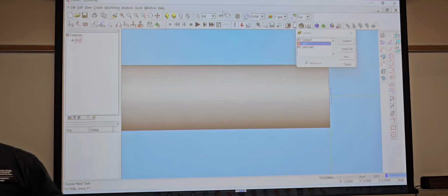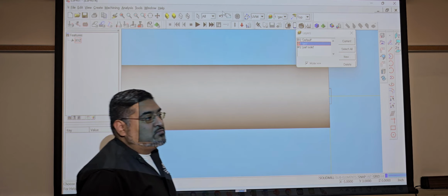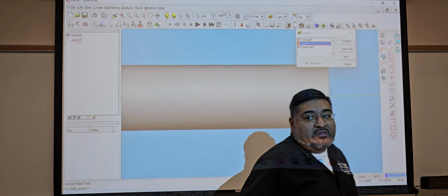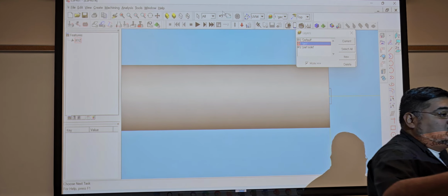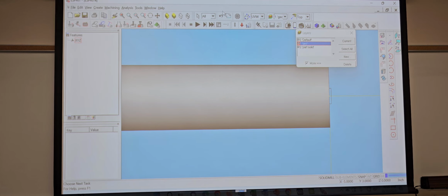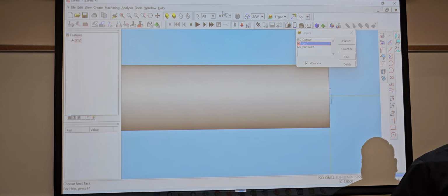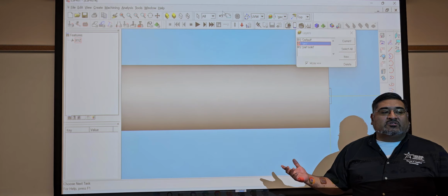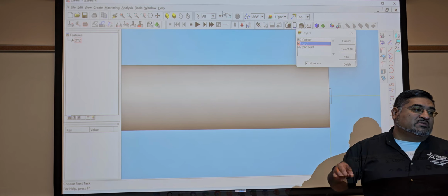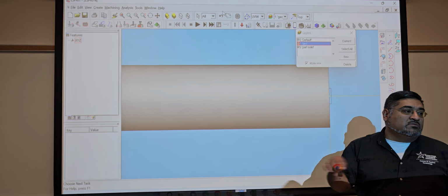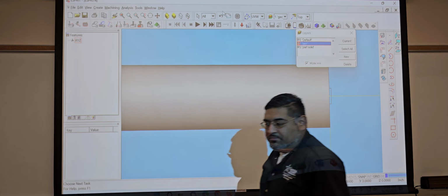Now, you could 3D print something like that, right? Yeah, but it's better to 3D print it with one that has a second filament, because you're gonna have no empty material, 100% infill. Versus just having one extruder and putting supports, because you're gonna actually need a lot of supports to be able to hold on to that material.